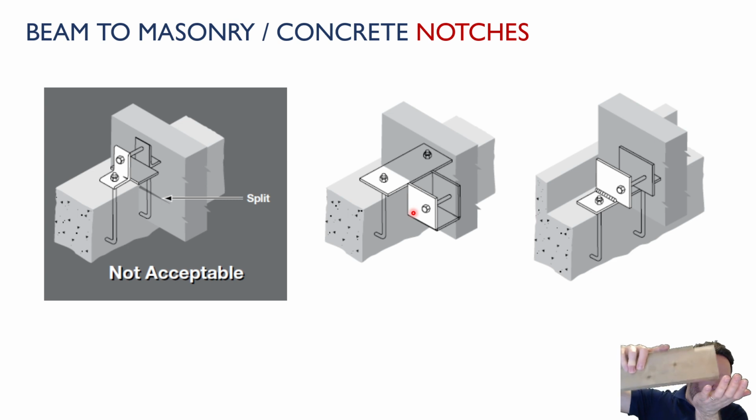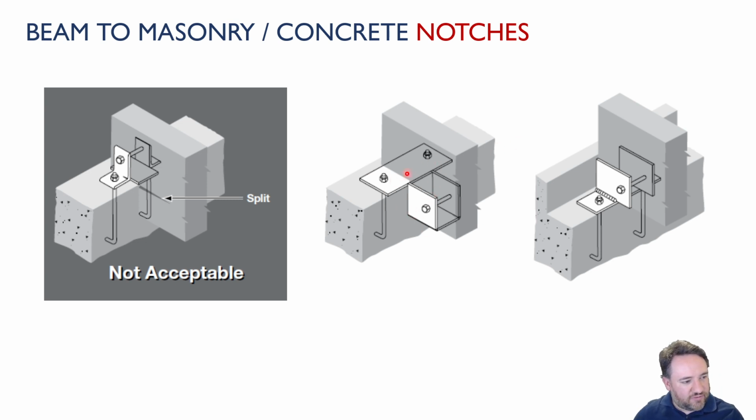I basically have my piece of wood sitting directly on its bottom, as we like our kindergartners to do, right? So we're gonna sit our piece of wood like this, which is much better than doing notch shear. So that's one option, to design kind of a fabricated connection like this to pick up the bottom of that beam.